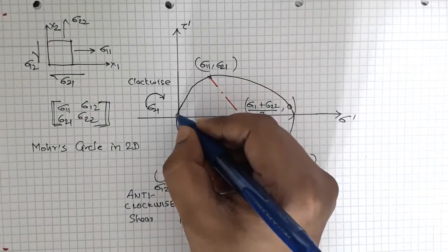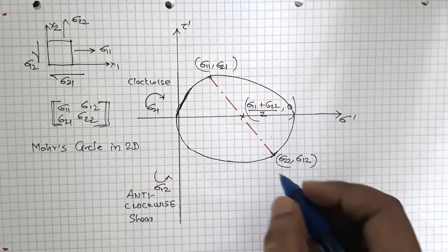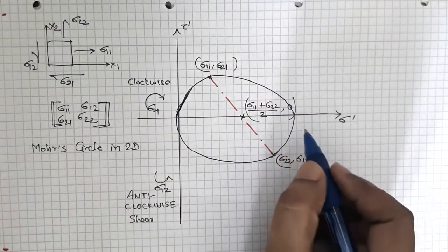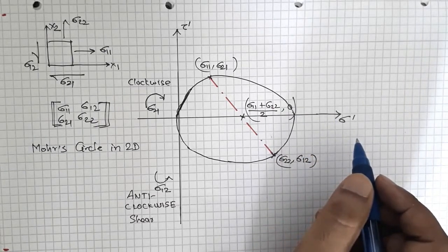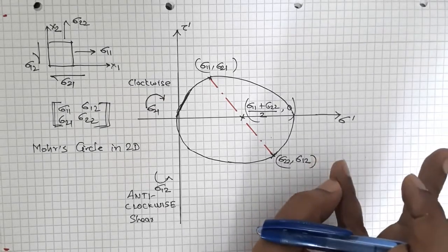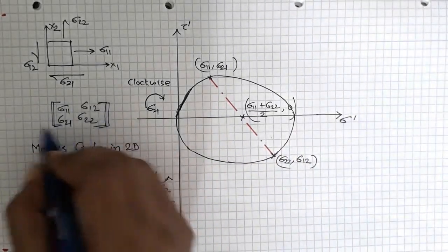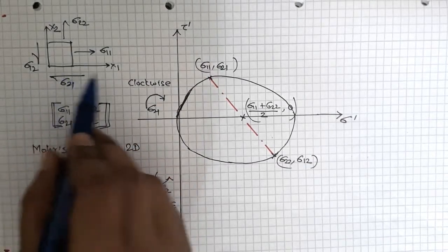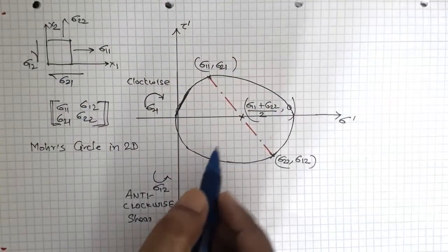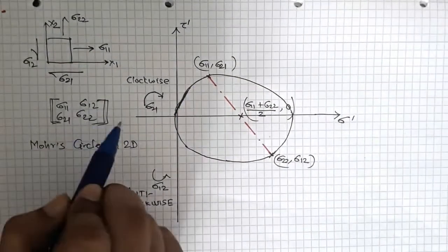So now what is the importance of Mohr circle? In the tutorial there was a question that, why we are rotating it, why we are not happy with shear stresses. There is no such thing that we are not happy with shear stress or we are trying to escape from there. It's just a property of this tensor. The state in which my stress component is now is described by this diametrical line, right?